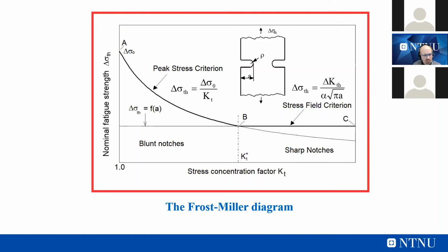It tells us that, first of all, the stress concentration factor KT is not a governing parameter if we have long cracks or sharp notches, because you are underestimating the fatigue strength of the notch too much, and so you are too much on the safe side, because the stress concentration factor is not acting anymore as a parameter that is suitable for fatigue design.